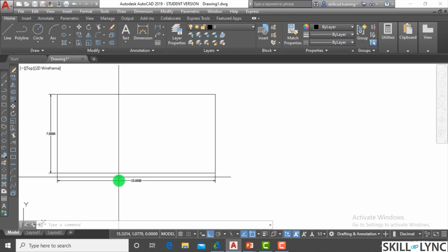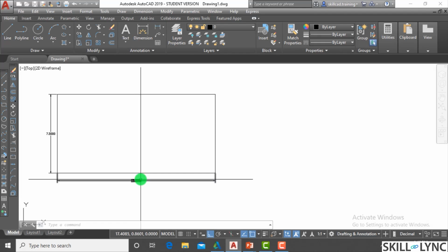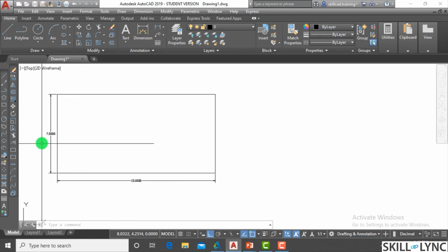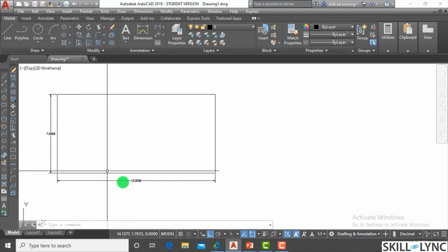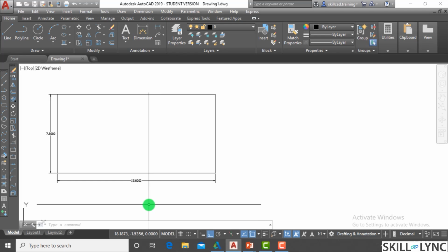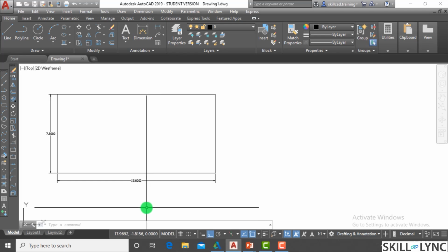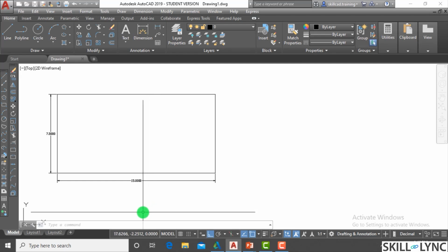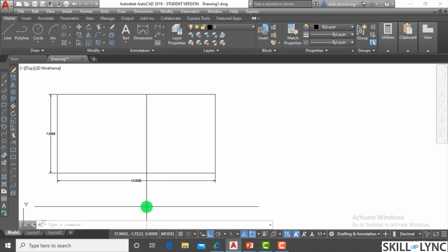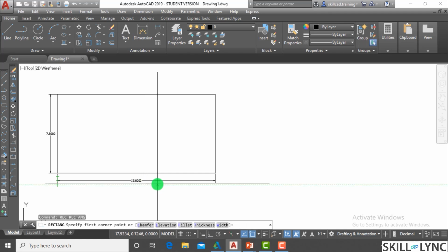So I don't want to put the scale factor. I want to put a length, the reference length and the new length. Then the other length will be automatically scaled. So it happens a lot of time that you are scaling an elevation, you are scaling a plan or scaling a section. It always happens in a drawing. So, and with the reference length, I'll tell you how.